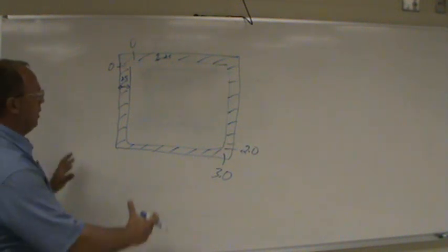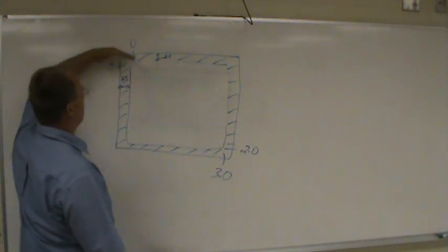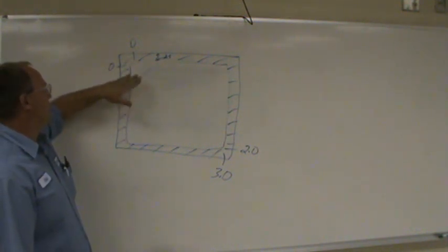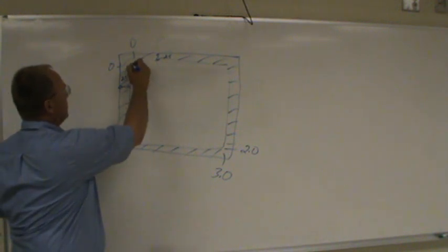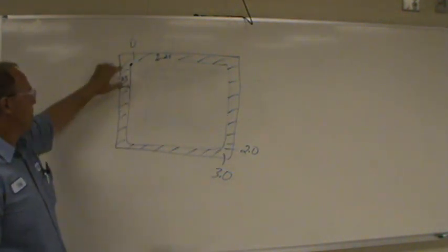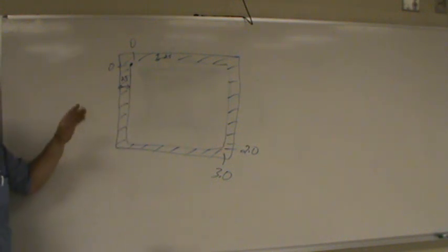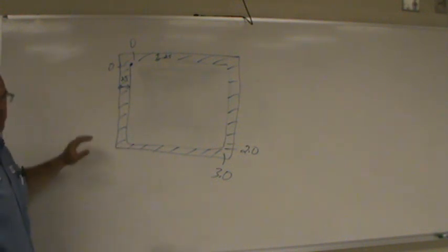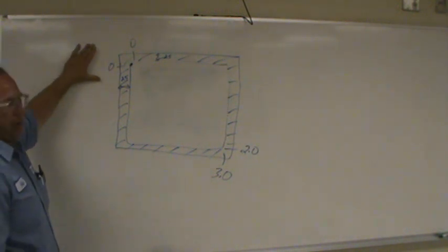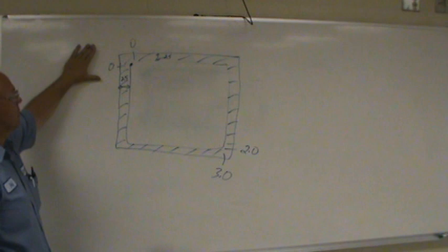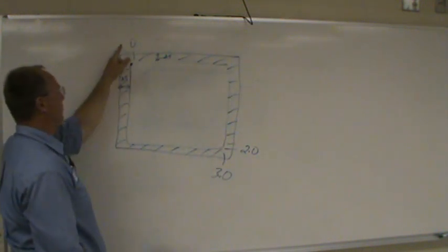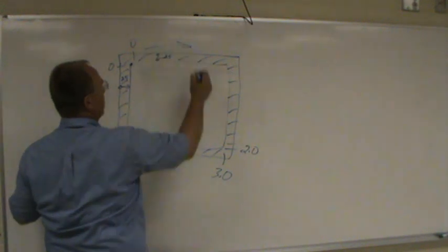So we put our part in the vise, offset our 0 with the edge finder, and then we also offset a 1/4 inch both ways. So our 0 corner is actually inside of our part, so when we mill around it, we're going to mill material all the way around so we have a nice square part when we're done. We know we're going to use G41. The climb mill would be going this way, right? This is the rotation that we want to go.